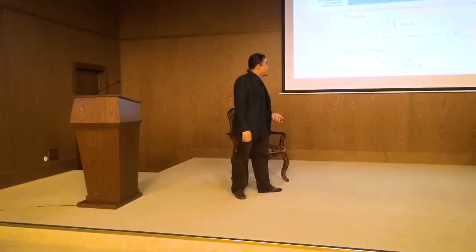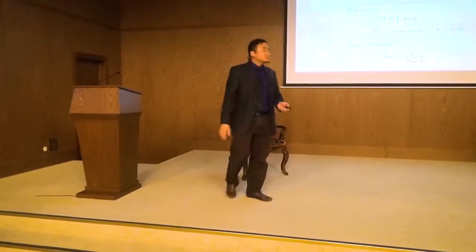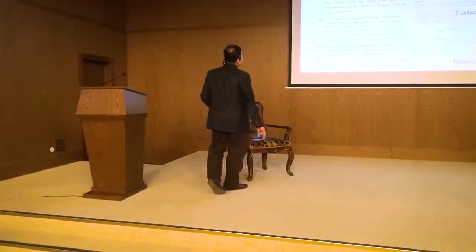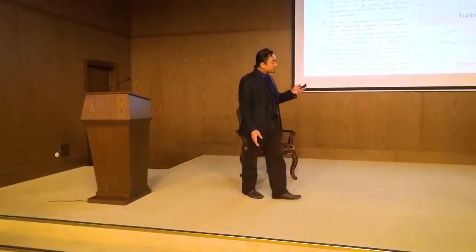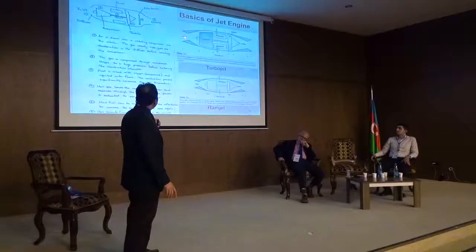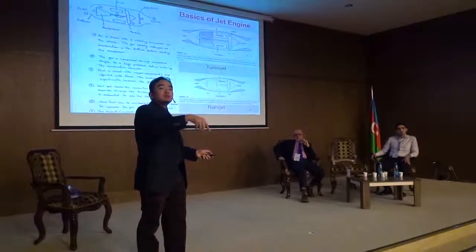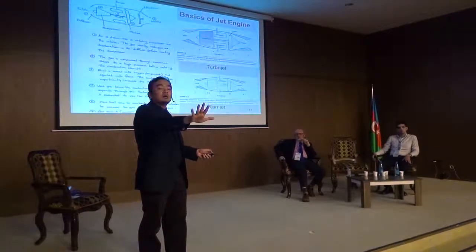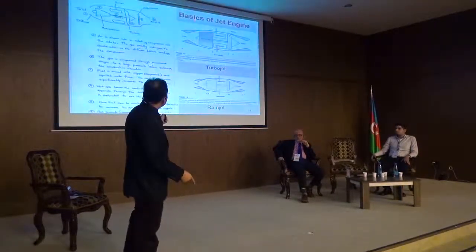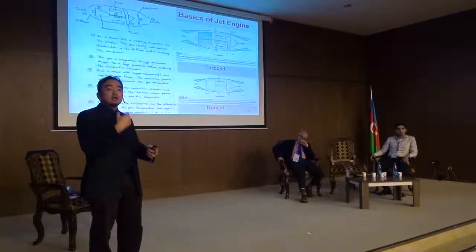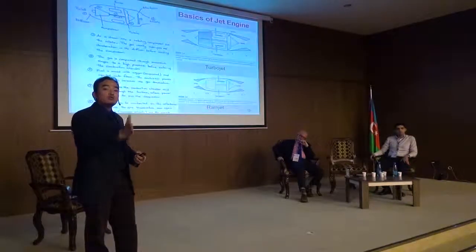And some other important parameters, but I'm not going into this in detail. I will skip this. But basically, these are the basics of the jet engine. As you're probably aware, we have the inlet here, where the air comes in, drawn in and decelerated because you have the converging and diverging nozzle, so that it can go into the compressor at a much lower speed.